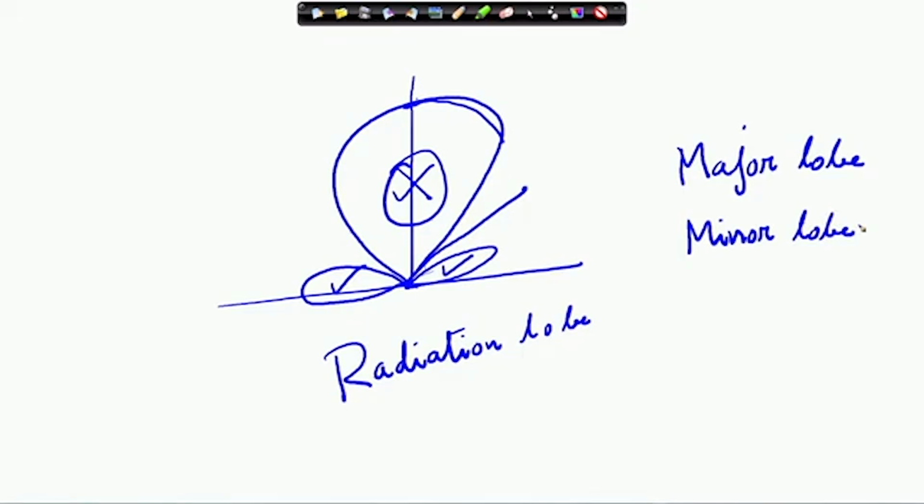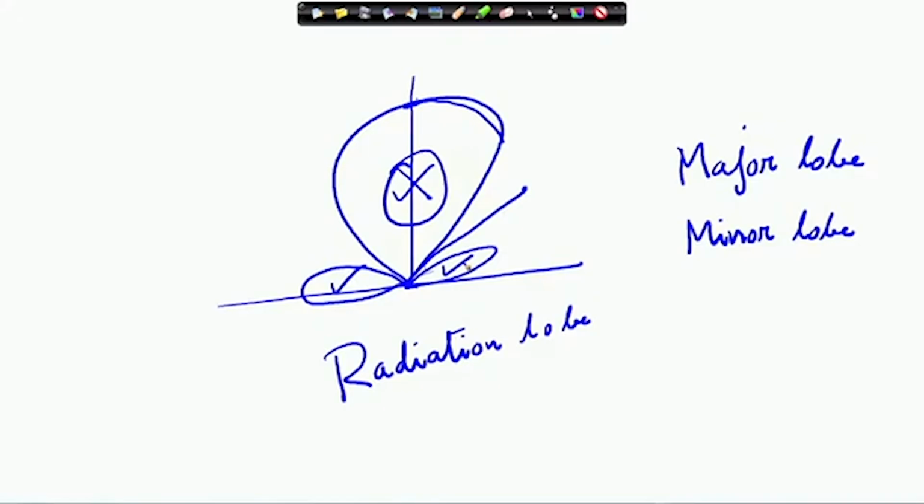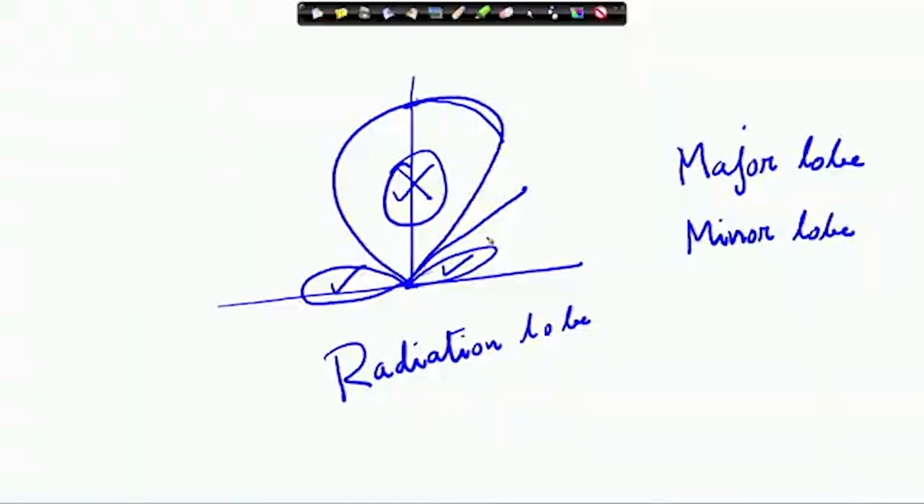Now, there are side lobes, some of these are side lobes, like this one is a side lobe. What is a side lobe? Generally the lobe in an unintended direction. I want that my antenna should radiate only in this zone, but obviously it is also radiating here. So, any interference that will come from that side, it will receive that also. So, it is an unintentional one. Where I do not want to put my radiation, those are called side lobes.